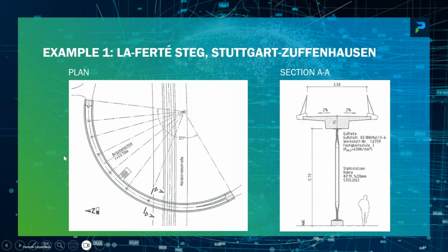When you have that kind of curved opportunity, you should see right away this is a great opportunity for making an integral bridge, even if the bridge is relatively long. You need to design this bridge so that this movement can happen. You see this in the cross section here at column number 1, right next to the road. We have only a 750 millimeter deep superstructure T-beam that's relatively wide because it needs the torsional stiffness. But the torsion is just handled at the abutments, and through the curvature there is an interaction between torsional moments and longitudinal moments, but I can't discuss this here in detail.